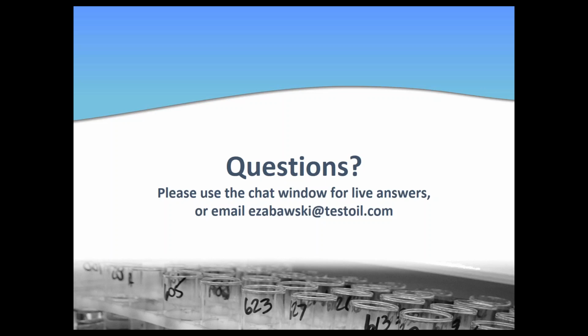The last question I'll answer at this time is one from Namrata that says, does the oil viscosity have any implication if we want to do particle count in oils? It indicates that she's left the webinar, so she's not going to hear this answer, but it is a good question. When it comes to particle counting, the viscosity of the oils does play a role depending on the type of particle counter that you have. If you're using a pressure system to push the sample through the sensor versus if you're using a positive displacement like a syringe drive, it has a significant impact in the accuracy of the particle count.